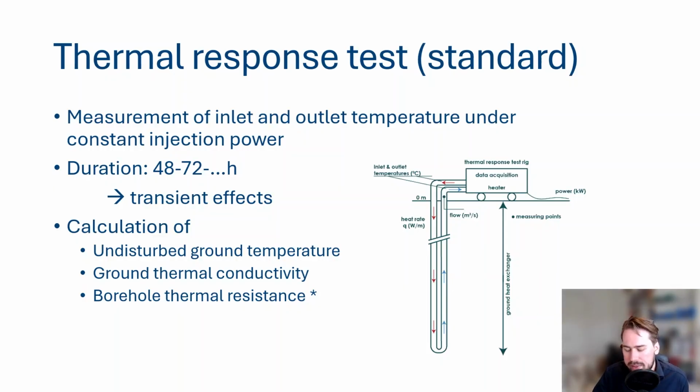So you need to be aware that this measurement, at least the borehole thermal resistance, should perhaps be corrected when you use it in your design, or perhaps even be ignored. And we will go over that when we hop into GHEtool later in this video.